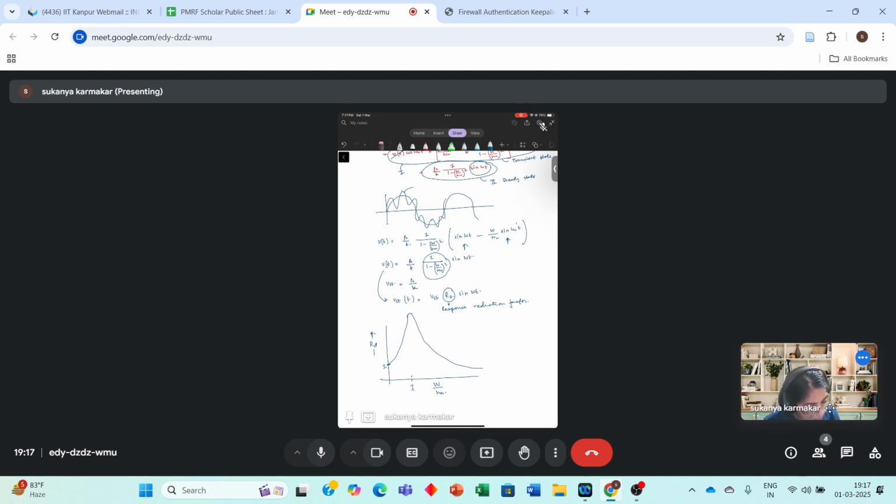So at this point, you know that this is the resonant amplitude. Let this resonant amplitude be some A. So here a point, like we draw a line where the resonant amplitude is 1 by root 2 times A, and these 2 points are noted. Why is this done? Because this is how basically we are relating the power in the systems, and these 2 points are marked, and this distance is known as half power bandwidth, and it is equal to 2 zeta.